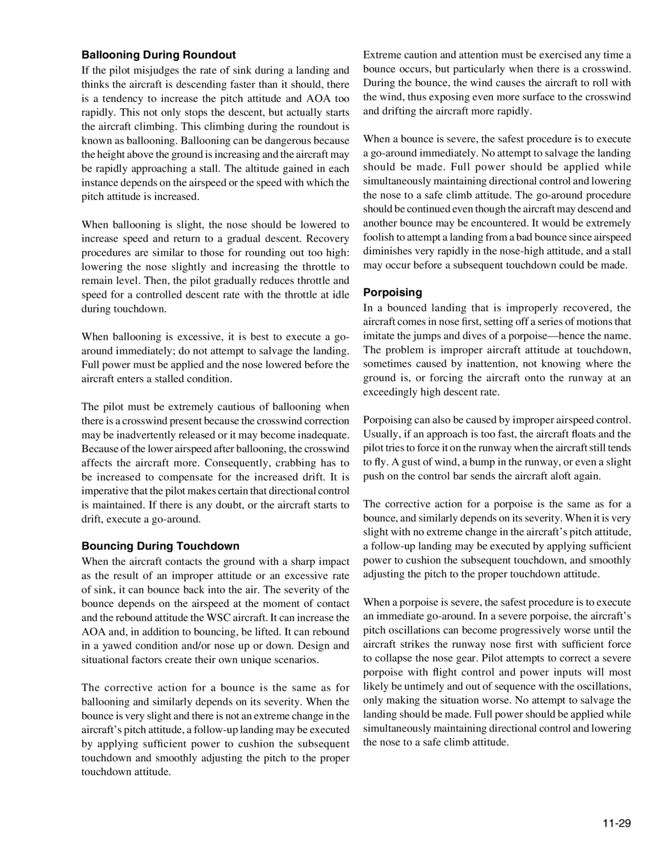Ballooning during roundout. If the pilot misjudges the rate of sink during a landing and thinks the aircraft is descending faster than it should, there is a tendency to increase the pitch attitude and AOA too rapidly. This not only stops the descent, but actually starts the aircraft climbing. This climbing during the roundout is known as ballooning. Ballooning can be dangerous because the height above the ground is increasing and the aircraft may be rapidly approaching a stall. The altitude gained in each instance depends on the airspeed or the speed with which the pitch attitude is